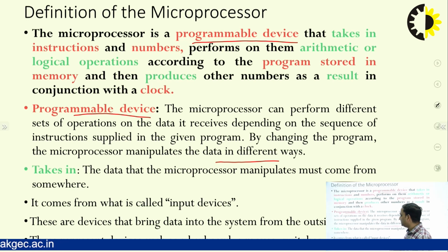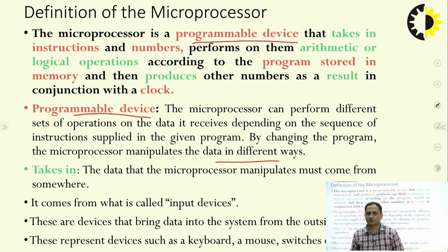It is a really tricky job for the microprocessor, which executes instructions by fetching them at the initial stage, then decoding and then executing. So these are the 3 operations any microprocessor performs: fetch, decode and execute. Every instruction is fetched one by one sequentially, which is why this is a programmable device that executes a program, and a program is nothing but a set of instructions. Every instruction will be fetched, then decoded, then executed.